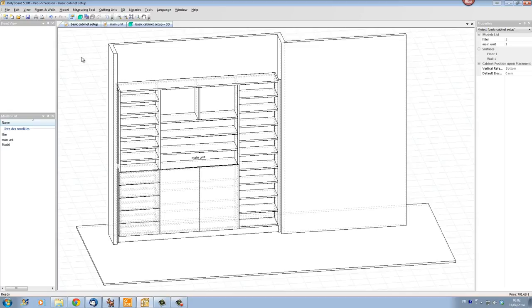When you're in project mode, you go into the menu measuring tool, and you have three possibilities. You can do 3D measurement, which means that you'll be able to click in 3D space and put in dimensions on your drawing that are inclined in space. Or you can lock the measuring tool onto a vertical direction, so any points that you click will be only measured vertically or horizontal measurements. Let's have a look at what the 3D measuring tool does for a beginning.